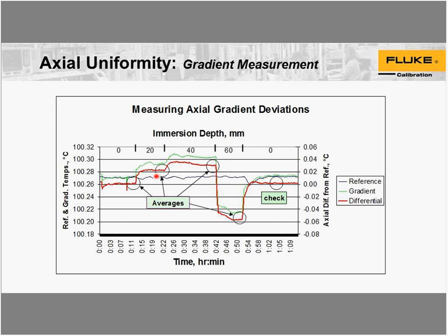So at some point, however, it will start to cool off naturally, and there's also a component here of stem conduction, which is going to drop your temperature towards ambient. So here we're at 100 degrees C, more or less. So we're increasing as we approach the center of the block. Then it would have probably started coming down, but we've got a little bit of an impact of stem conduction. We'll describe the stem conduction problem in a little bit.